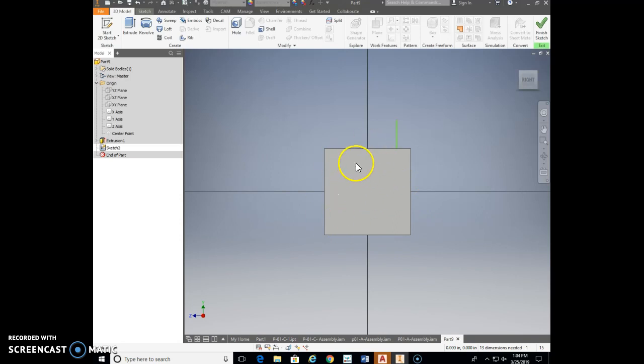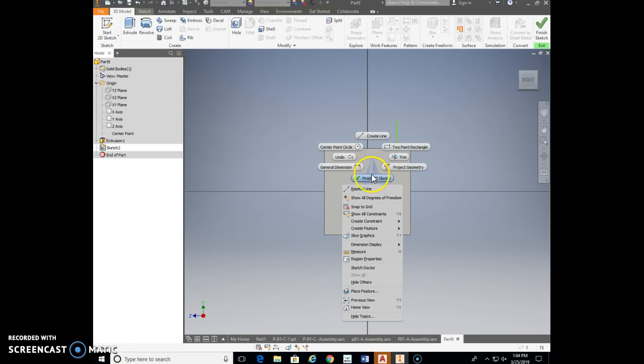I'm going to right click on the screen right here on top of this block. Do you see anything in this list that may be something you think we might need to do so I can see those lines? Not Hide, there's not. You might think that one. Anybody else? Not features, what? Slice, I heard somebody say? Slice graphics. So click on that one that says slice graphics.